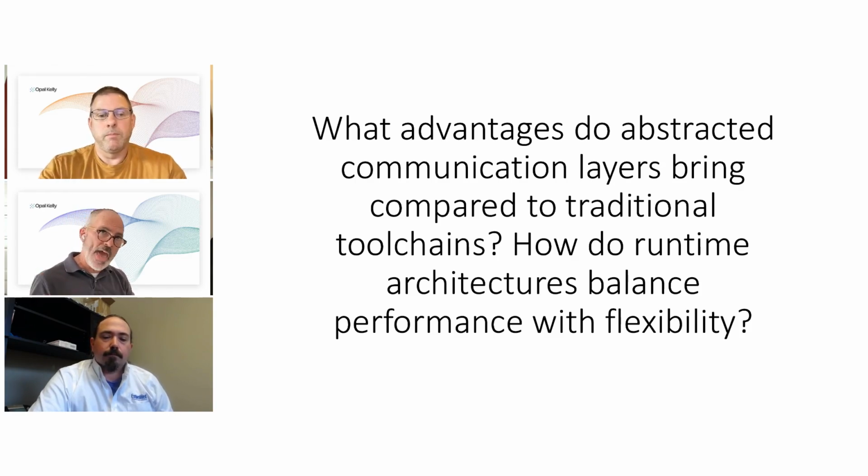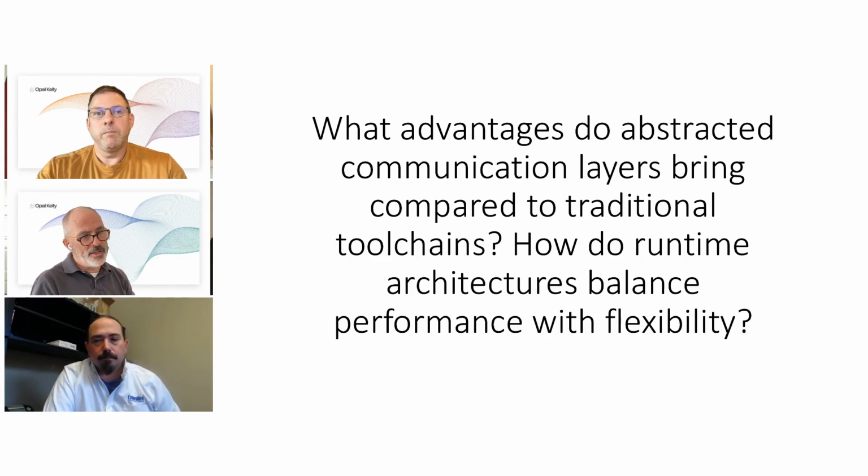So the other one that we'll touch on a little bit is the ADC, DAC, sensor interface to the FPGA. That area, one of the ways is the FMC bus, the FPGA mezzanine standard, that's been around a long time. It's a big, expensive interface. It works pretty well for larger systems. It has a pin count approach that matches well with FPGAs, but it's often overkill for the kinds of systems that our customers are developing.